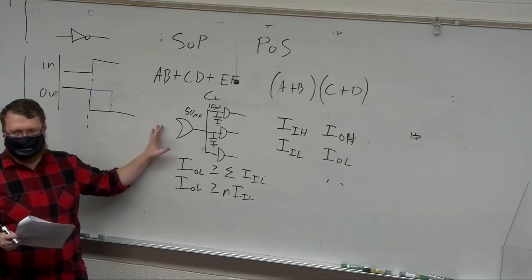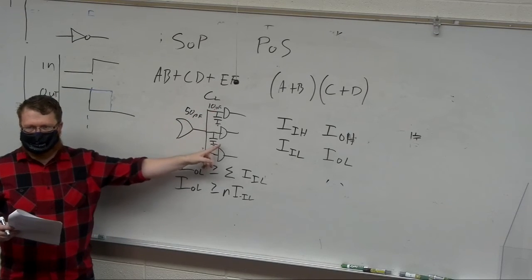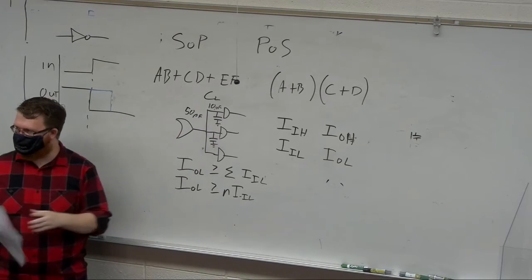So if you're doing the calculations, you figure out all the devices it's connected to, add them all up, and see if it's less than the output. Straightforward.